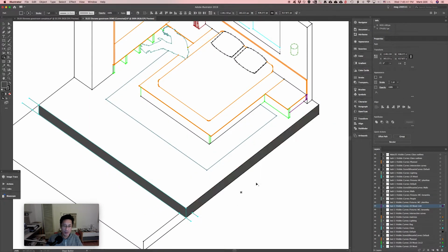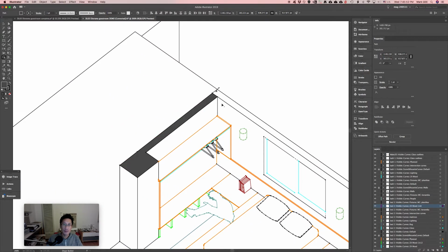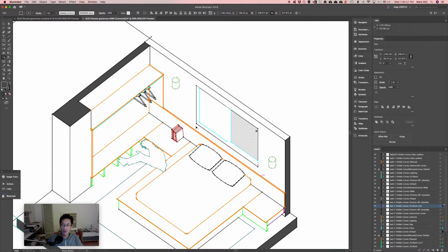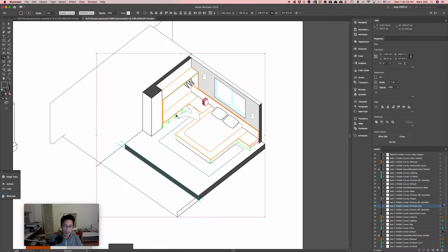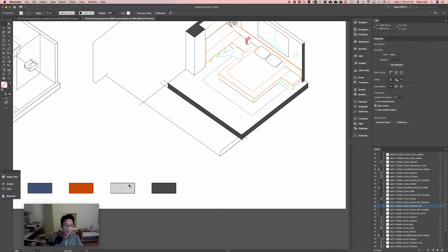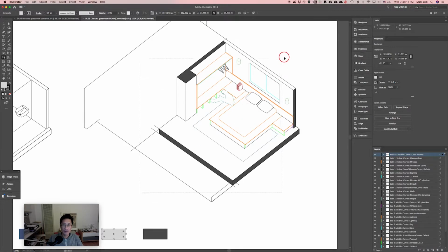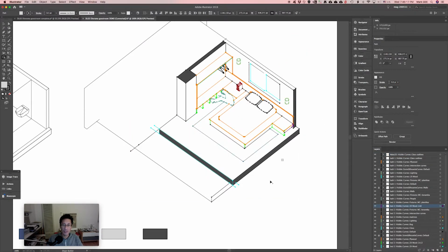We'll connect those two together. Show this wall section cut, the ceiling, and that one we need to do separately because I think that's a silhouette, a line back there that I've locked actually, so the Shapebuilder tool is not working on it. So we'll just have to do that one manually. We'll do the next color, select the color, switch to the Shapebuilder tool, Shift M, picks up that color, hold down Command, select the objects we want to work on, let go of the Command key, and it's there ready for us to apply that color.